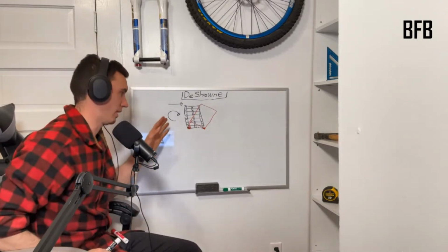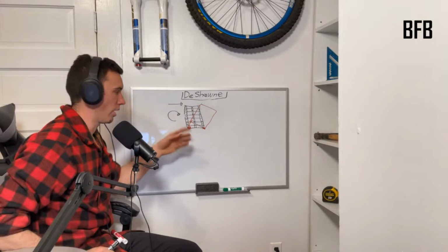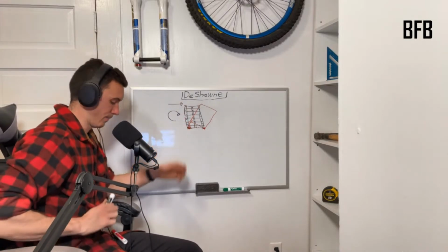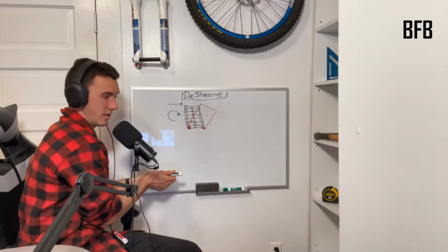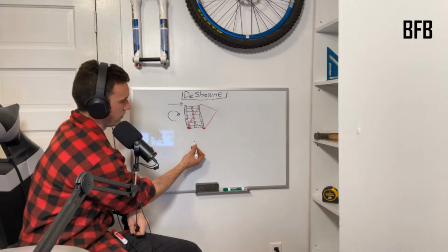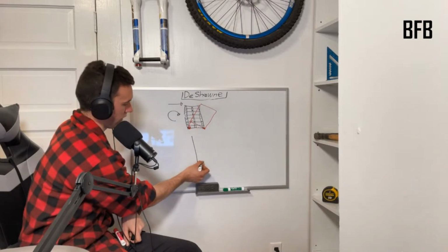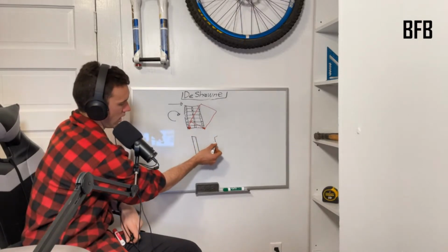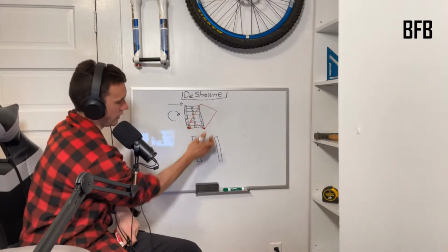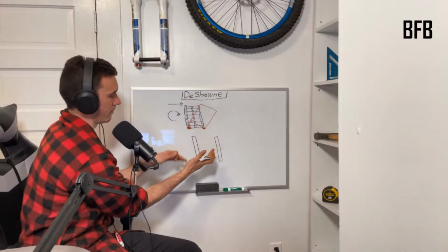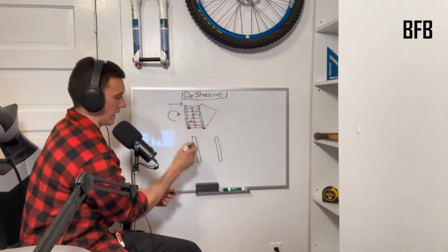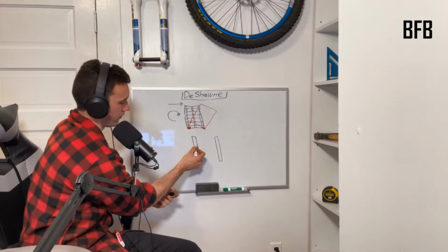Well, the answer is probably no, because now you've introduced a bunch of breaks in the plane. However, you can still add strength just like the planks do. And this is how. So in a very basic situation, we're going to have a block and a block. I could put one sheet on this whole thing, nail it to this, and then it'd have a good rigid plane, a good rigid diaphragm. But I don't have a sheet. I've got one plank. I'm going to put that one plank right in the center.